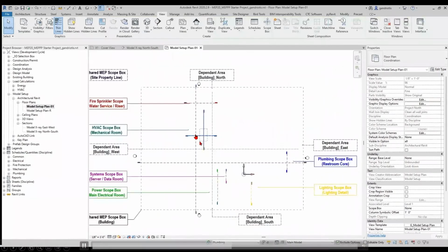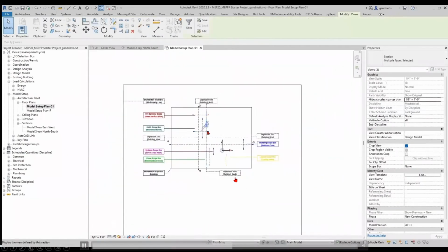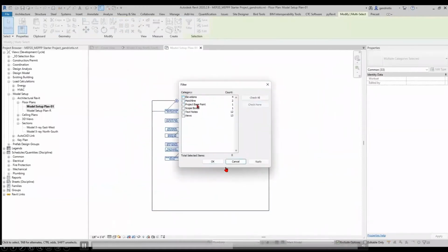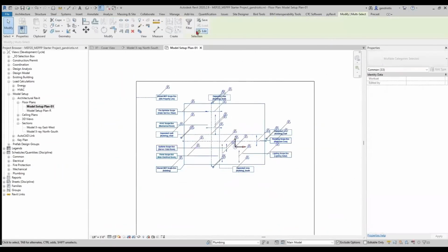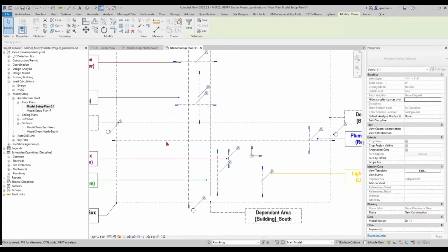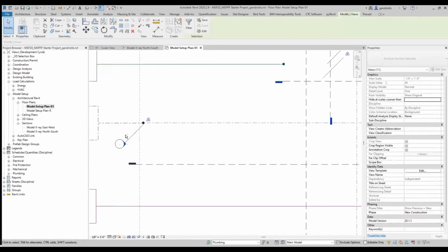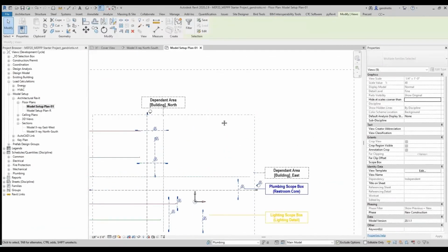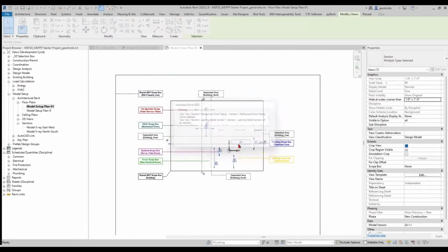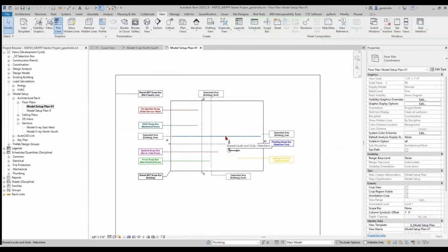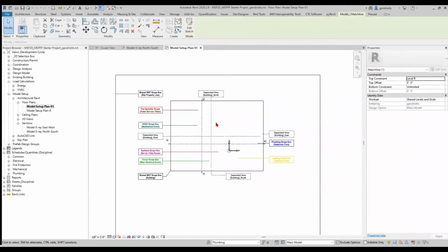Next up, I'll hit these elevations, the views. Sorry, elevations. And I have to be clear here. Don't just hit delete. You've got to look, because you've got some north, south, east, west elevations. I don't want to delete those. So real quickly, I'll deselect those, and I'll deselect those 2 in the middle, the north, south, east, west view, the main view there. And then I'll delete the rest. So you'll see that just those 2 and then the 4 north, south, east, west remained.